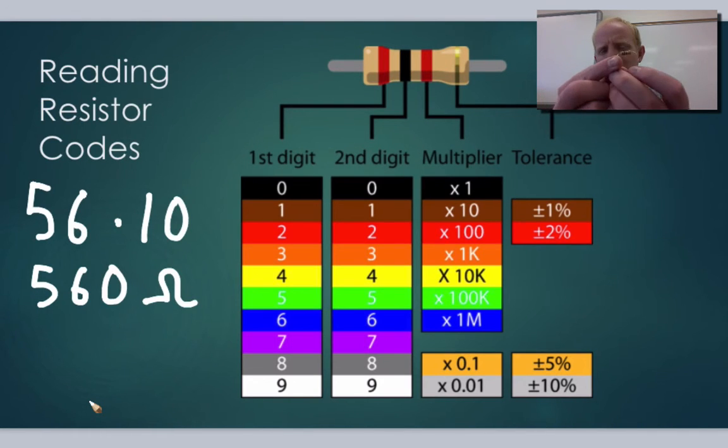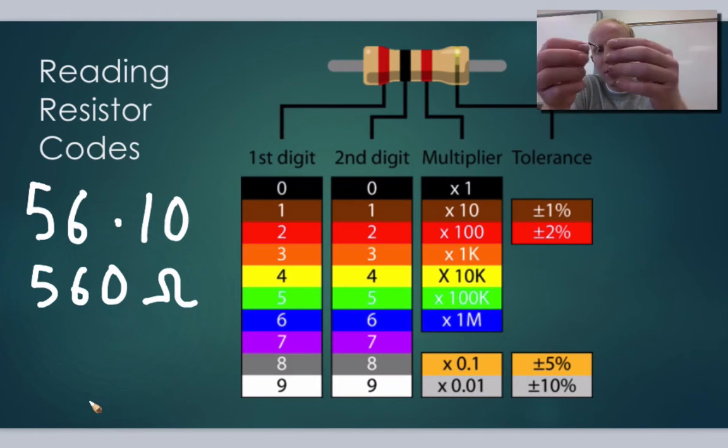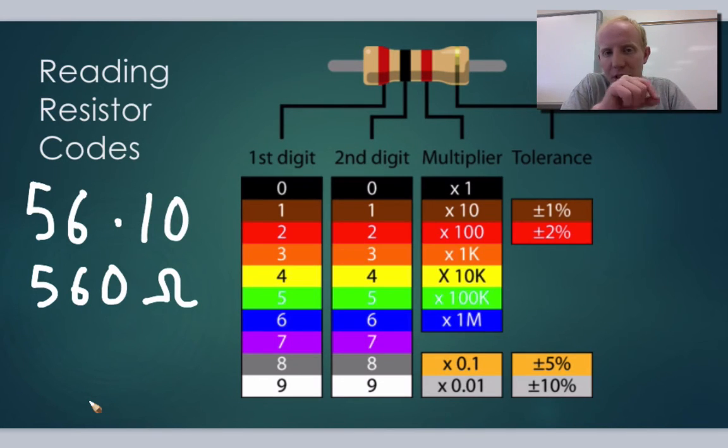But keep in mind, there are some pretty small resistors, and especially at computer level, they don't even use this same system. But the color bands are very helpful because even at small scales, you can still see the colors even if you can't read the print. They could see that the resistors were going to get smaller and smaller, so they used colors instead of actual numbers so that you could determine the resistance even if you couldn't read the small text.